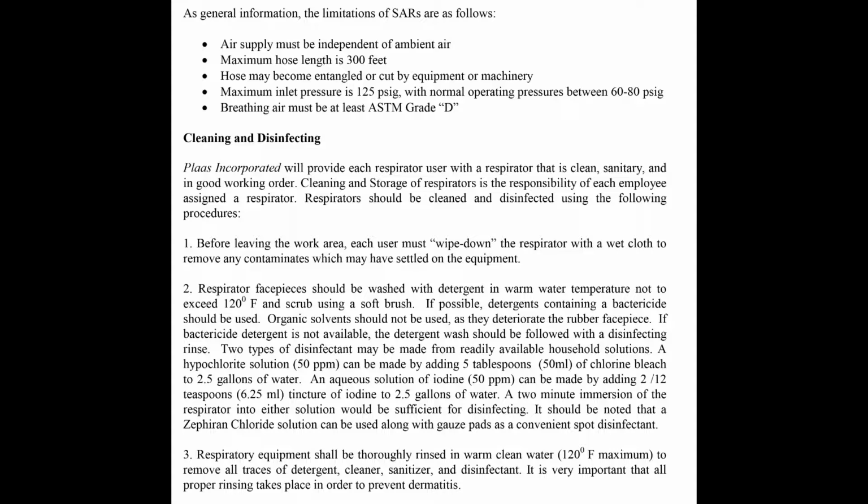Cleaning and disinfecting. Plaas Incorporated will provide each respirator user with a respirator that is clean, sanitary, and in good working order. Cleaning and storing respirators is the responsibility of each employee assigned a respirator. Respirators should be cleaned and disinfected using the following procedures. Before leaving the work area, each user must wipe down the respirator with a wet cloth to remove any contaminants which may have settled on the equipment.